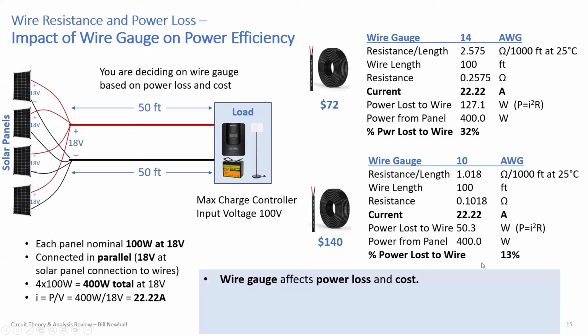Okay. So the whole point of this exercise, the slide I'm showing up, is that wire resistance matters at higher current and longer distances. So if you have some project where you have a power supply that needs to be far away from its load, and you need a certain voltage at that other end where the load is, you have to consider the voltage drop. And if it's a portable or battery powered or solar powered application, power lost to heat in the wire is a consideration.